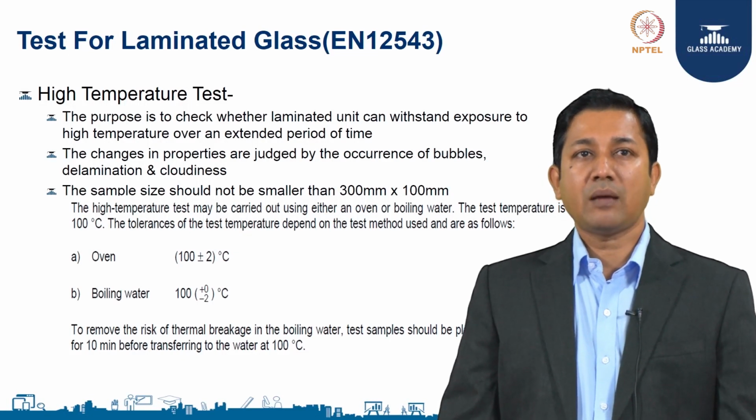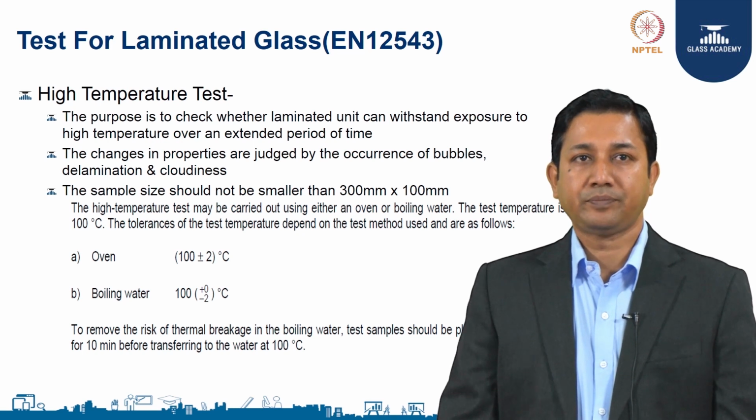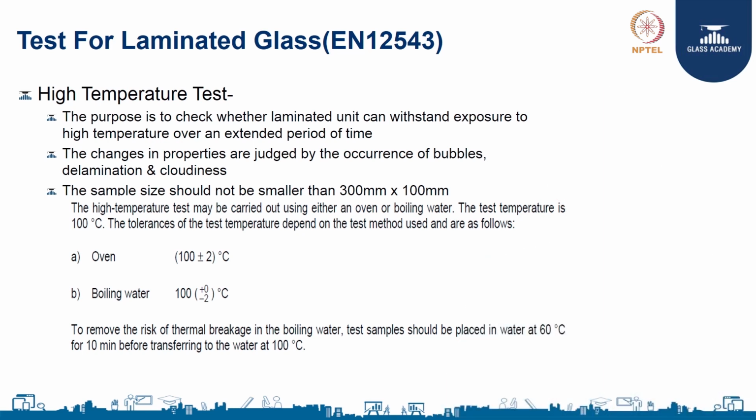For this test, the sample size should not be smaller than 300 by 100 mm. The tolerance should be plus 0 or minus 2 degrees centigrade. To remove the risk of thermal breakage in boiling water, the test sample should be placed in water at 60 degrees centigrade for 10 minutes before transferring to the water at 100 degrees centigrade.